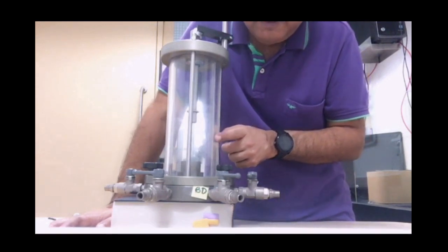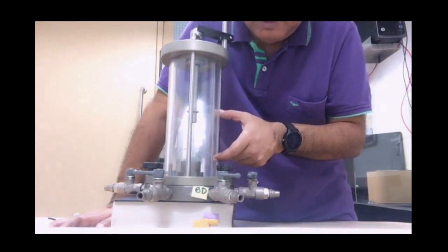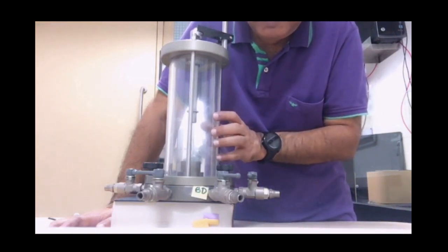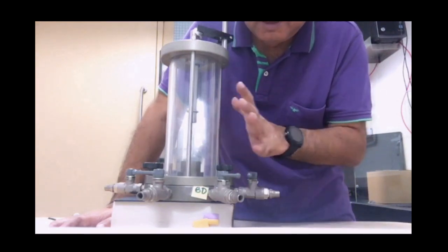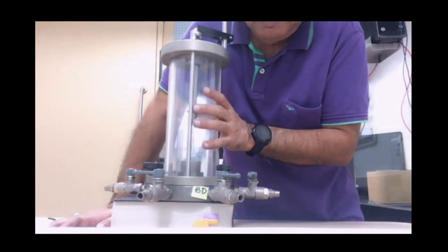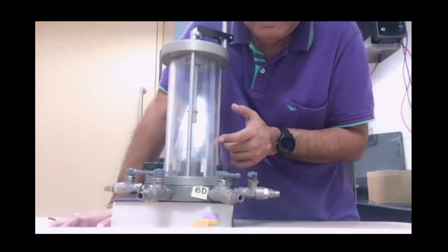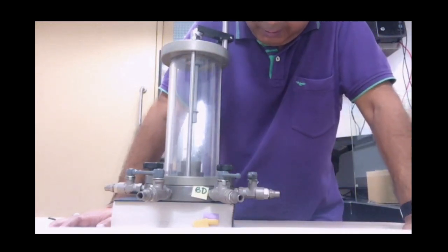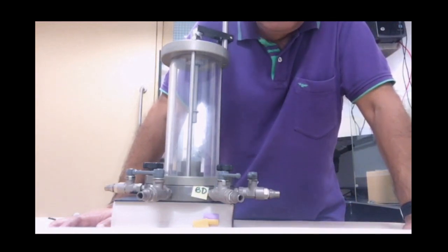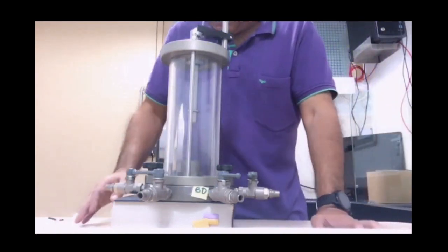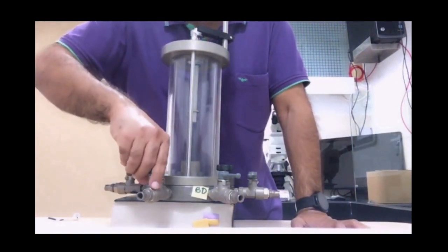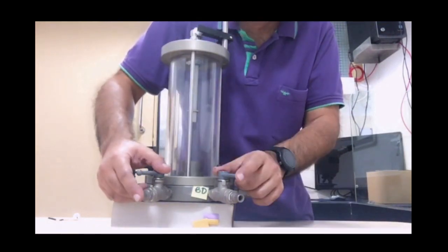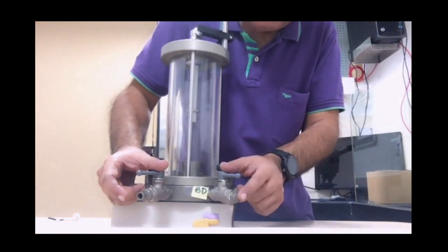One precaution which I have to observe is, if the pressure in the sample is on the higher side, higher than the cell pressure, then the sample is likely going to burst. It's going to be a small bomb. It will just explode. So I need to have the cell pressure higher than the pressure inside the sample to maintain a slightly positive effective stress. Okay, we have just discussed this. How do we do that? So the way out is, I increase the cell pressure. Keep it at a slightly higher value compared to the back pressure.